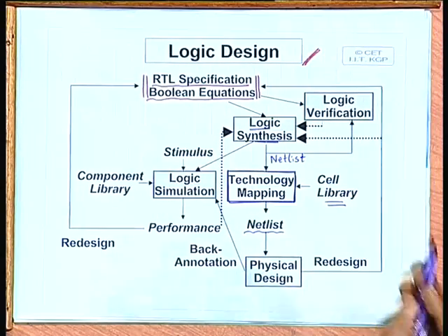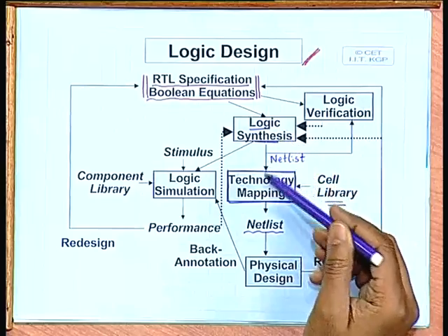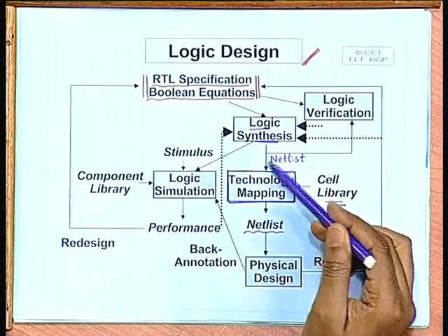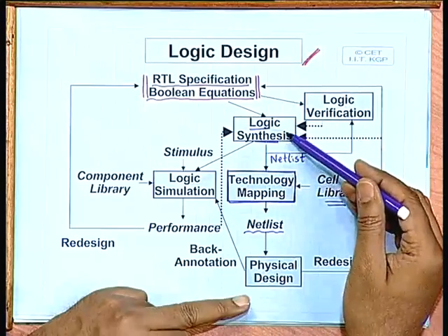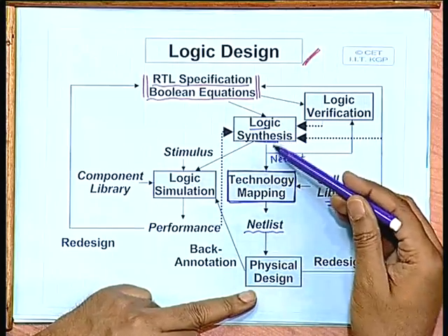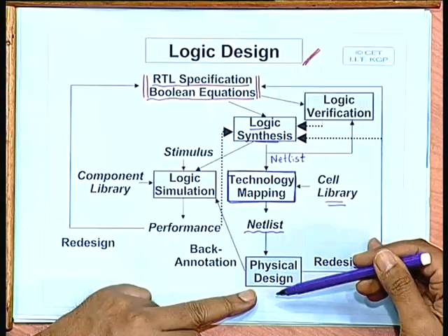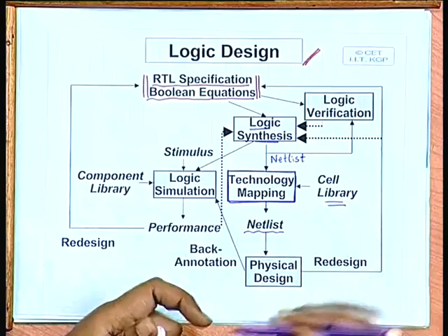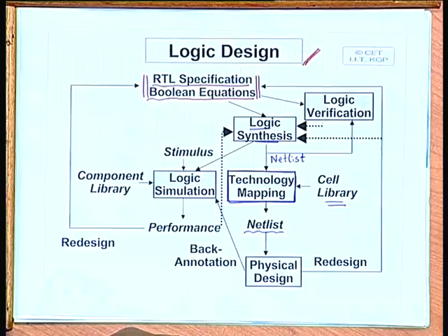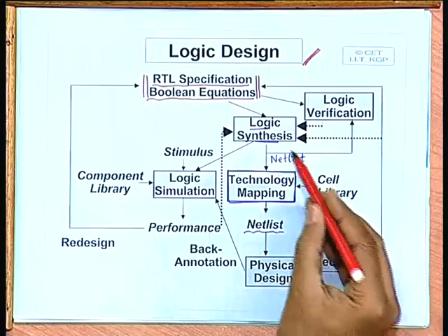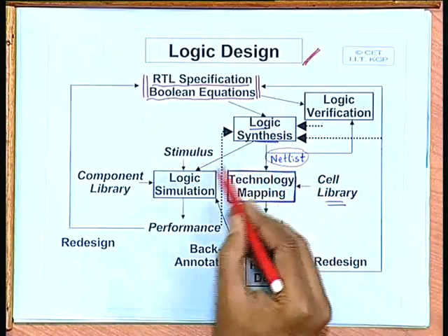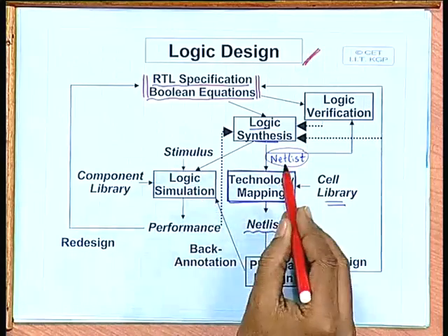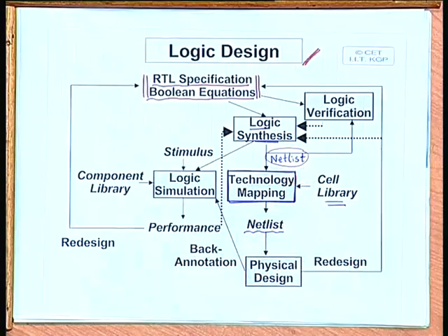But as you can see, once you do the synthesis and physical design, you have incurred a lot of cost. If it is an ASIC design, you will have to go through the entire steps of the ASIC design process, which is expensive. So, usually what people do before going for the actual physical design is take the netlist obtained by the synthesizer and check whether this netlist is working as per the specifications or not.